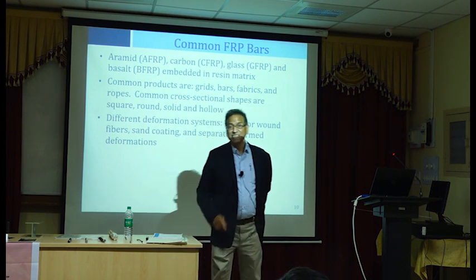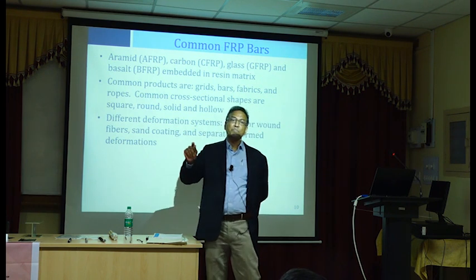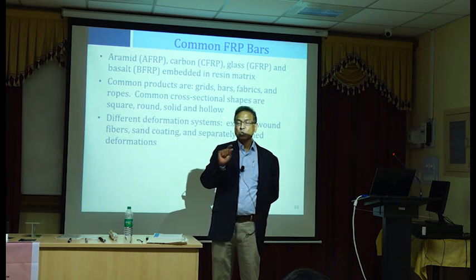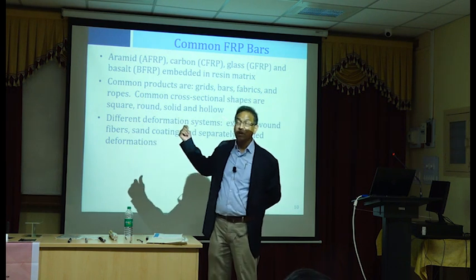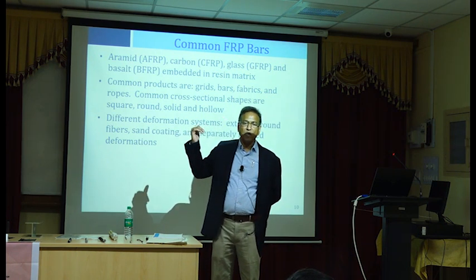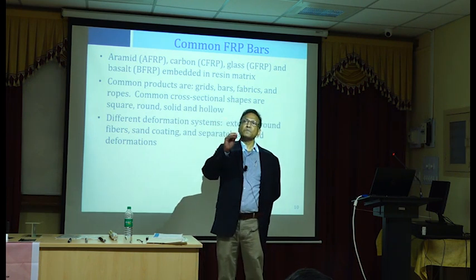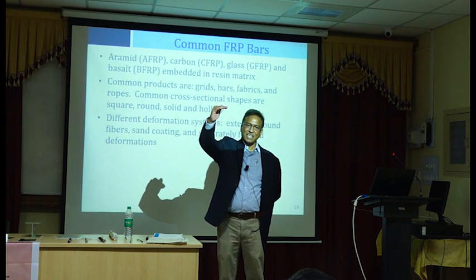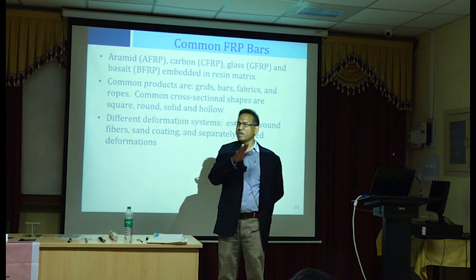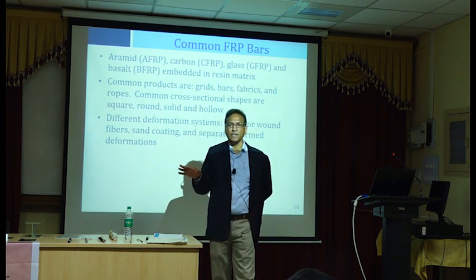What you are talking about is creep in concrete. This creep rupture refers to the creep rupture condition in FRP bars. Maybe the day after tomorrow, I will present creep rupture design, where you will see that we can only allow up to a certain amount of stress under sustained loads. That's a problem. Whereas with steel, you don't have to care about sustained load acting on steel.